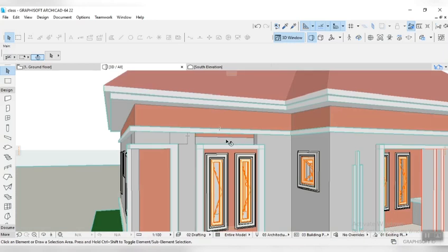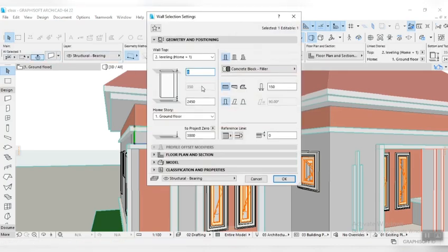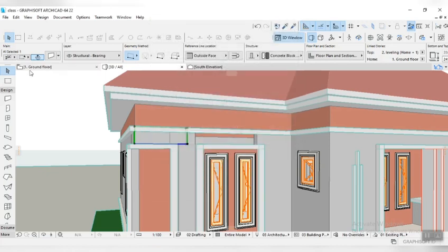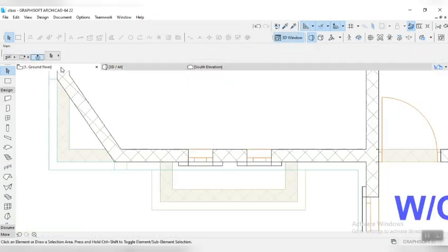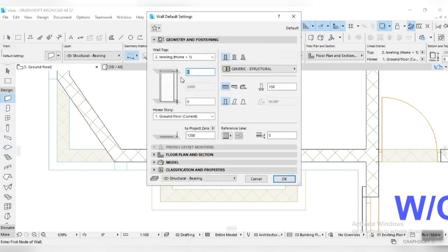Let's look for how to fill this volume. Okay, I got a wall for that. What's this wall? This 350 by 2450. So we'll come down here, take the wall tool, go to wall settings, come here to 350, then we'll do here 2450.